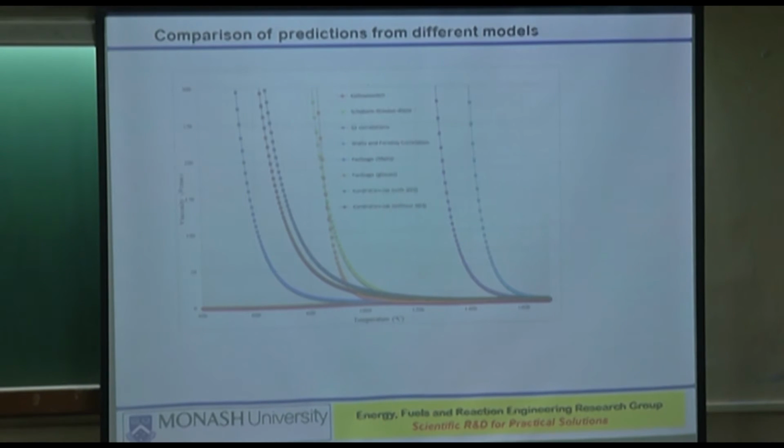It can melt beyond a certain temperature, but it cannot melt fully at that temperature unless you give it sufficient time. So, the ash fusion temperature measurement is not the sole predictor, it is a complementary first cut information,